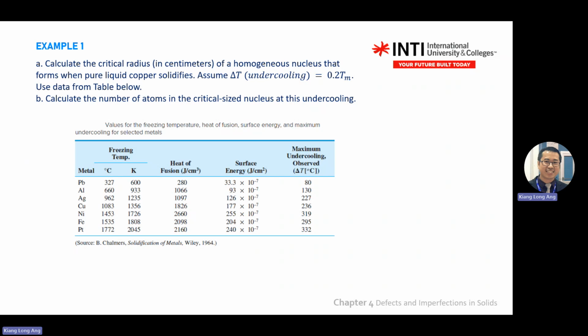It's at the phase where it starts to turn into a solid and become stable. Means you reach the critical radius already. This temperature will give you this stable nucleus. You can start to see this size under a microscope already.